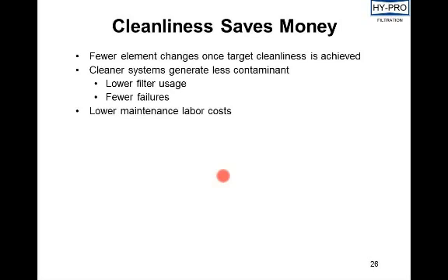If we're able to keep the fluids cleaner, we have fewer breaks and repairs on servo valves, pumps, and cylinders that fail due to contamination-related issues. So we're actually able to lower our maintenance and labor costs if we use the high-efficiency DFE rated filter element.